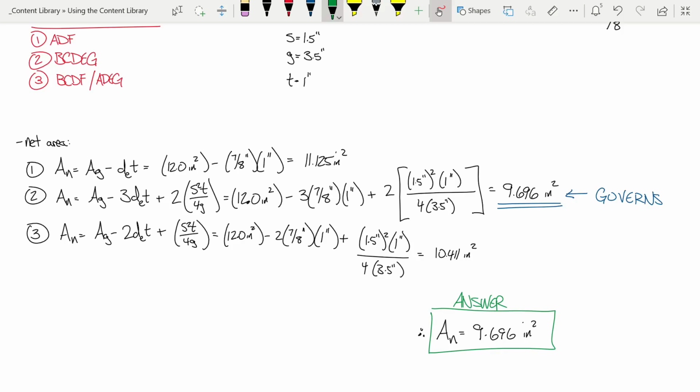And I know that some of you are going to go, but come on, that's getting a little ridiculous. There is a reason, okay? Here's the reason. I'll give you a real-world example of a member where you need to check all the paths. We're probably going to look at a member like this a little later in the semester, but this is an angle where there are staggered bolt arrangements and the stagger crosses one leg to another, okay?